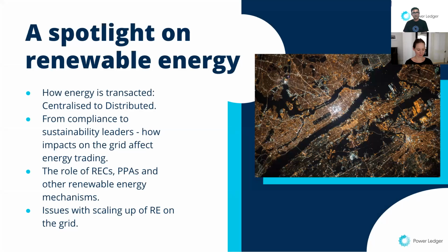Whilst technologies like solar and wind have been great, bringing the prices down as well as making the grid green, it's not without its own challenges. Ask any grid operator, the integration of renewables is a huge challenge. Some of these come from the fact that energy is now flowing in the reverse direction as well, from people's rooftops back to the grid. The daytime load is also affected by renewables like solar, which are supplying and are variable, and of course intermittent. So it poses problems of scheduling of synchronous generation, which is what previously supplied electricity to us largely. Interruption in that system also causes energy system security risk, as well as problems with reverse flow of energy to grid infrastructure itself.